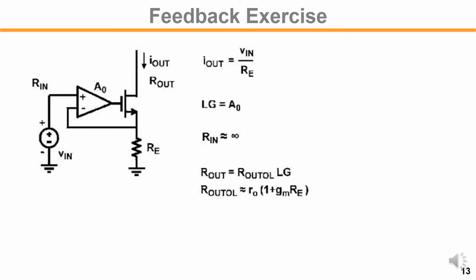Let's take a look at some examples of the negative feedback circuit here. This is constant current generation. So there is a negative feedback here. Let's say if the output, this node voltage, goes up, then the amplifier output goes down. So this is a kind of negative feedback.